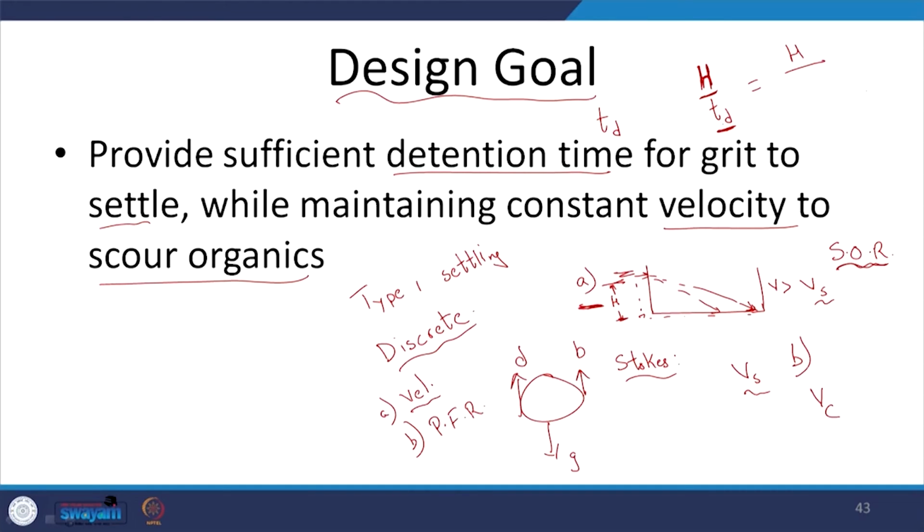But what does this time depend upon, or what is this going to give me? It is going to give me the time that this particle or water is going to stay in that particular tank. So, it is going to depend upon the volume V by the flow rate. Let me just write that out here. So, that is going to be the height; volume is length into breadth into height, by flow rate Q. So, let us try to simplify this further. h cancels out. So, I have Q and length into breadth, and h is the particular depth.